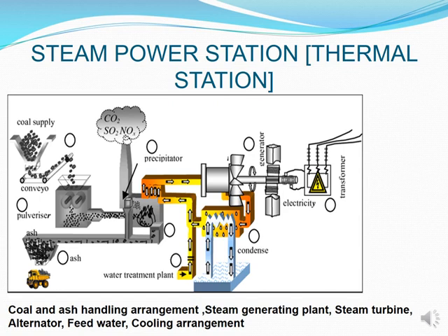So on this slide, we're looking at the process of how all of this works. So you've got coal at the top left-hand side, that is your supply coming in. It goes into something that is on the gray here called a crusher. And then from that crusher, which now takes these granules of coal and basically crushes them into something that almost is powdery, it gets then transferred into what we call the furnace. And basically, the furnace is where the coal is then heated.